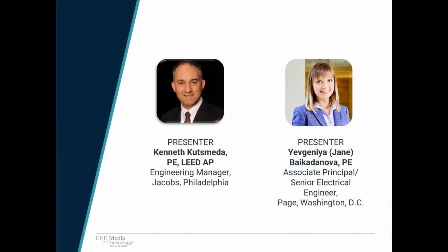When would you use resistance grounding for medium voltage? Yeah, that's actually a great question and something I didn't cover. But a lot of times you'll see in medium voltage systems, resistance grounding, it's basically to limit the amount of ground fault current flowing into your equipment, specifically a lot of times on generators, the generator winding and so forth that just can't handle that amount of ground current. You'll see adding ground resistance to help with the ground fault protection.